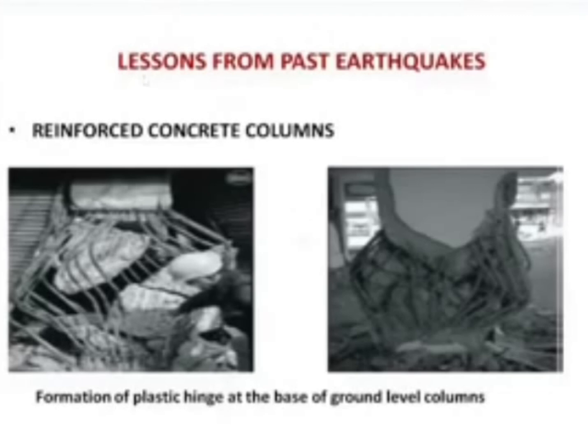You see, it's a typical reinforced concrete column. And at the base level, if the column hinge is formed, a plastic hinge is formed, what does it mean? Means this particular section here at the base level cannot carry any further moment. It cannot sustain any load.